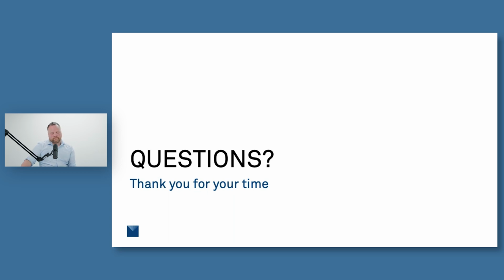All right. This next question, they're asking, does the sample need to be a virgin undisturbed sample, or does it need screening? So this is a great question. Normally what we recommend is trying to use as close of a sample to what you're trying to measure in the field. This can be tricky if you have a very cobbly soil. Obviously that's not going to work very well with trying to insert a needle into it. So if you have soils that have large stones or cobbles, you can remove those and just repack it to the density that you might have had naturally.